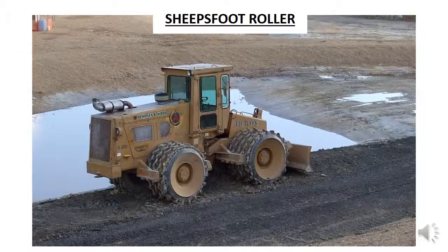This photo shows a sheepfoot roller. Note that the rollers have knobs on the rollers. This roller also has a blade at the front which allows it to push the soil out into a thin layer, which removes the need for a separate bulldozer to do so.